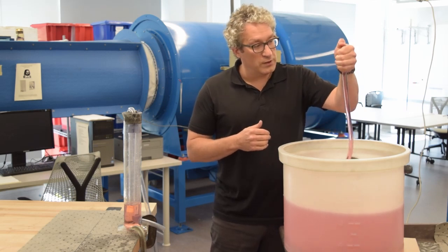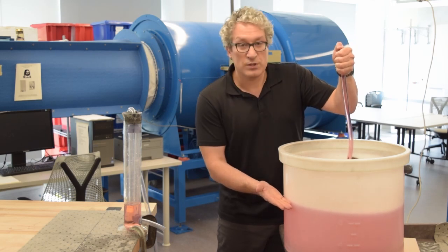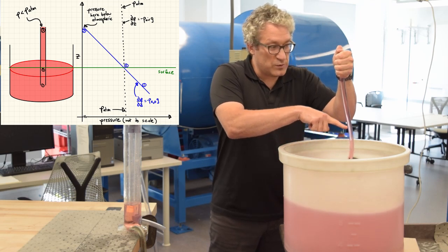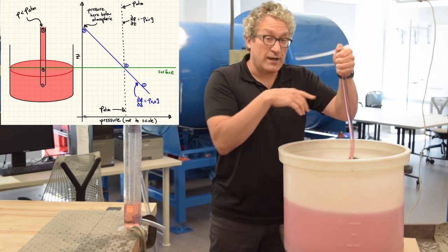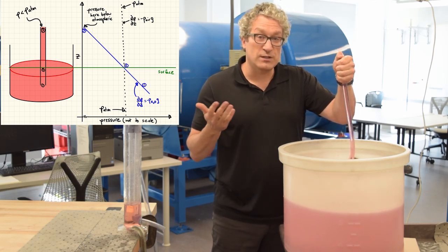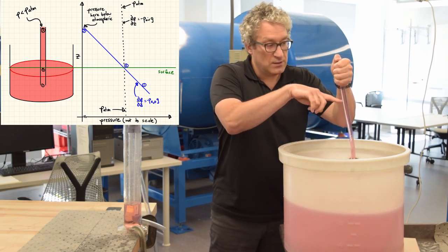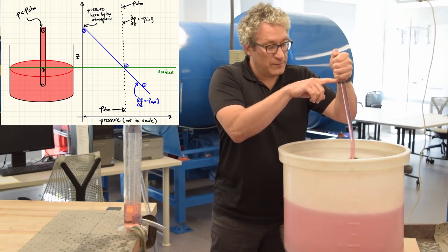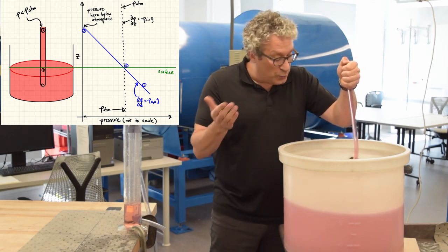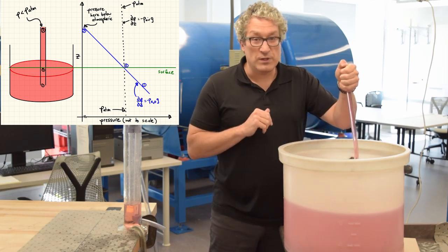And that means if I hold this tube of water, we can see that the water has some pressure here at its height, which is equal to atmospheric pressure. As we move up in this tube from the surface of the water to where I hold my hand, the hydrostatic equation has to apply, which means that the sum of the pressure plus rho times g times z has to be uniform. As we're increasing the z-axis, we have more gravitational potential energy. As we decrease z, we have lower gravitational potential energy. Also, for the hydrostatic equation, as we increase the z elevation, we must be decreasing the pressure.